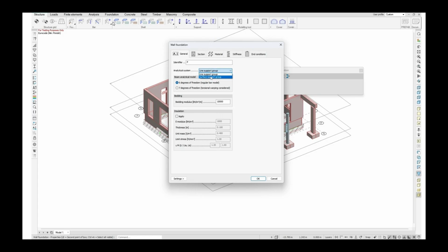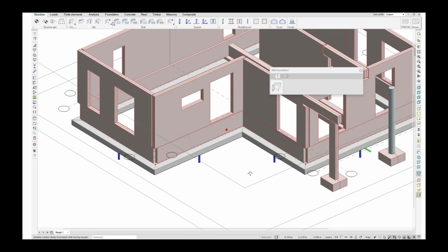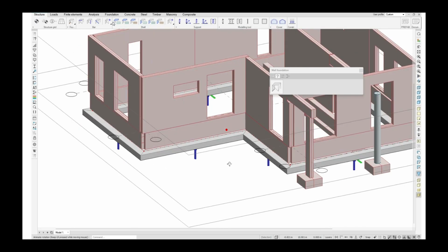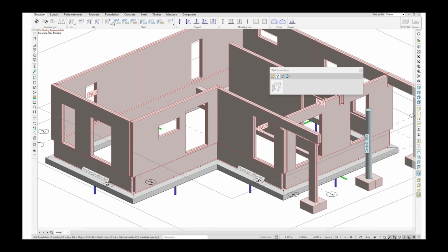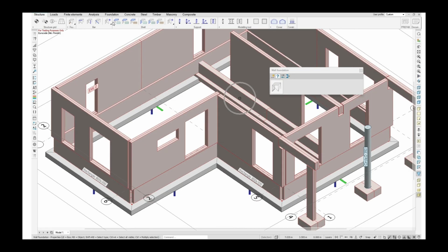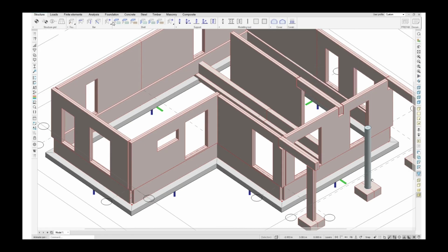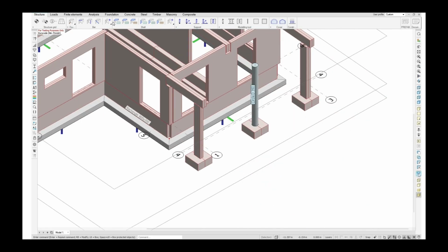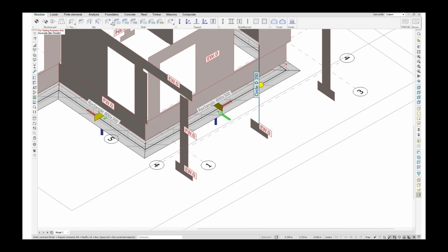So let's set the surface support. It means that now with the shell model, we actually have what we want. And if you have a piling plate, you can convert them to normal plates. So you can set your pile split like offset. Then we have this one element here and these elements which are not correct. How do we handle these? We can try to open the plain plate command and convert these IFC objects to plate and see what happens. But that is basically what we don't want. Now it's vertical. So how can we fix this one?